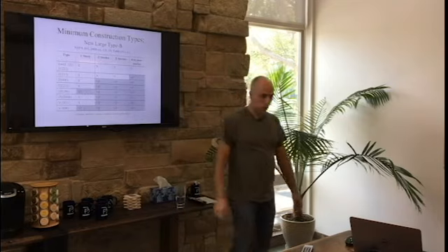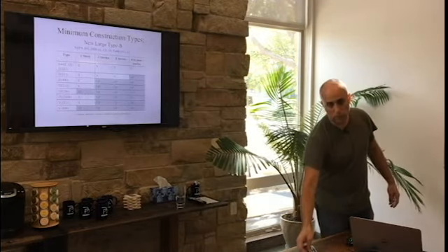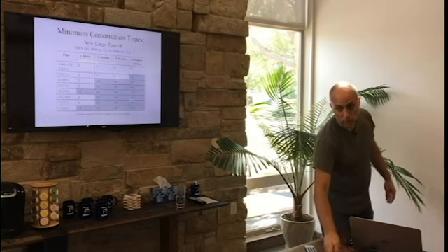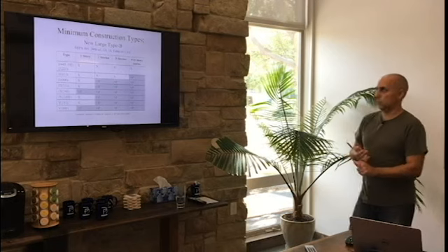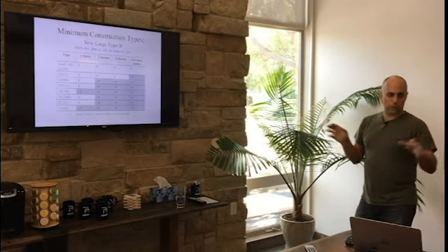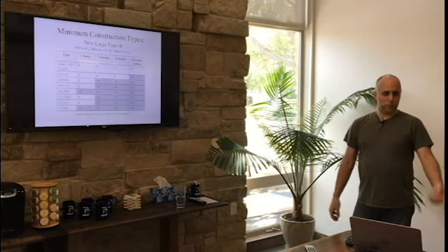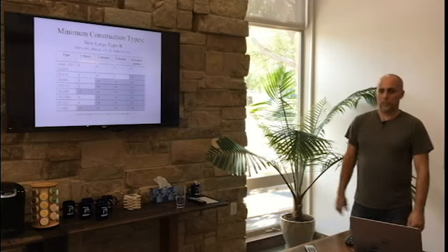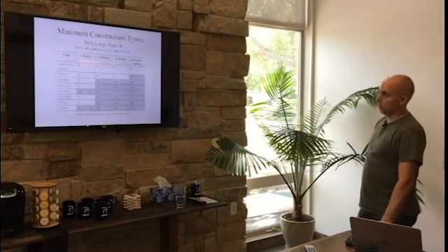You can do an unprotected, no rating, all non-combustible healthcare facility. So all these 1-story nursing homes and 1-story assisted livings that we do, they could technically be all done out of metal studs or all steel and have no rating whatsoever. But it's a lot more expensive than wood construction, so typically that's not what's done. But as soon as you go to multi-story, you have to go to non-combustible.